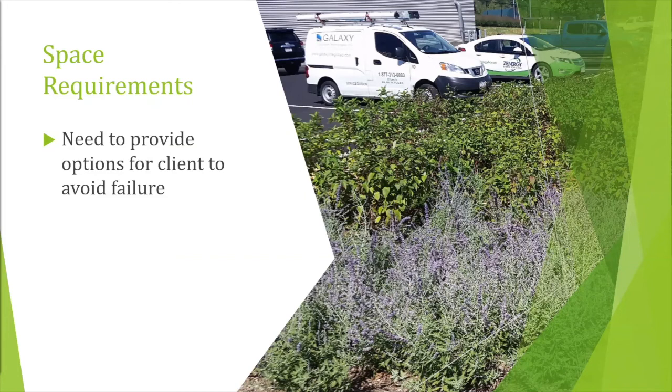We walked them through the maintenance for cleaning out a closed drainage system versus the maintenance for the bioswale, and the cost of losing 8 parking spaces wasn't a cause for concern at all, based on the cost they were saving from using a natural filtration system. This has an under-drain system and one little clean out, so they just have to back truck it out once a year. The landscaping is all natural to the area, so its maintenance is very low. We got rid of all the grass, so no mowing. It was all just natural vegetation, so it was really minor as far as how it needed to be maintained.